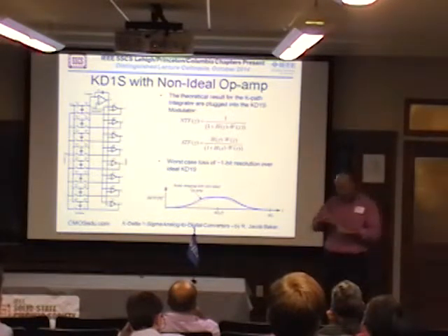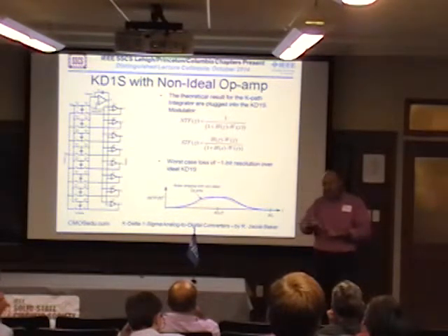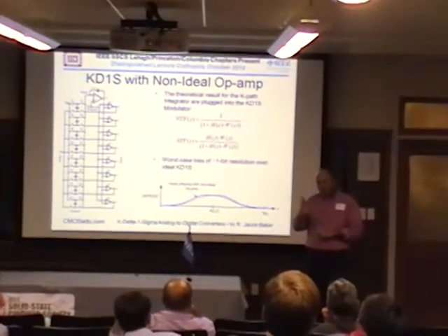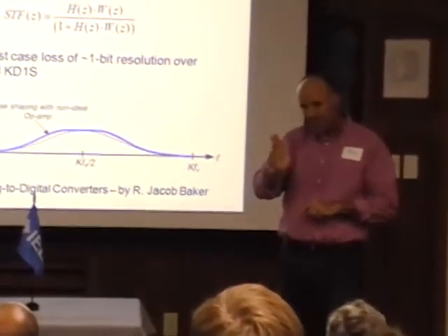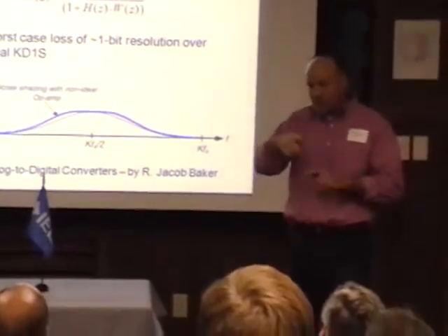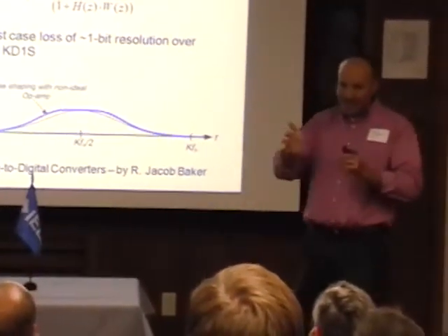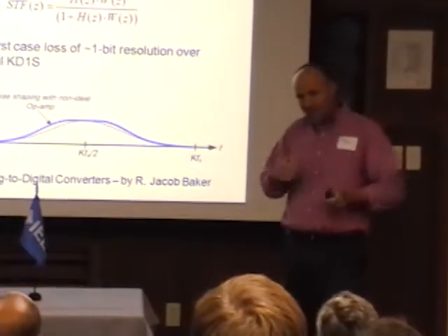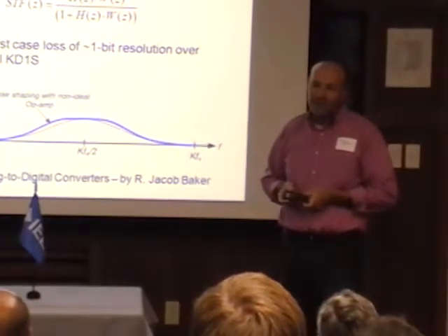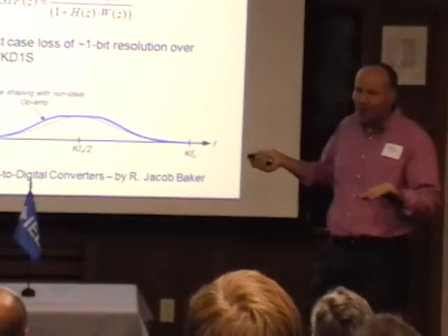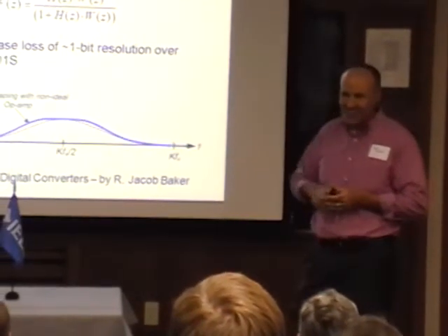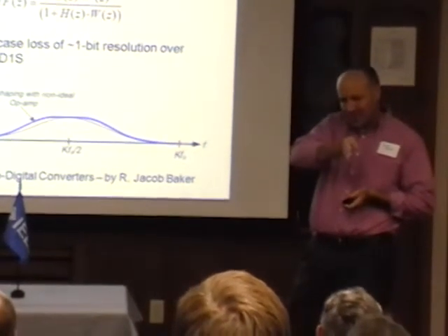Now there's a couple other things. One, of course, the finite rise times. I don't know how that would come into play. The DLL may not produce a truly random rising edge, right? We may get something with the DLL, especially if you're putting in an input signal that's synced to the clock frequency, where there's some residual timing issues. That's a very big concern. The fundamental thing is that you're averaging the clock phases, which is good for data converters, because if it's too early on one, it's too late on the other, and the average works out.